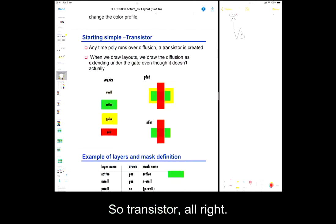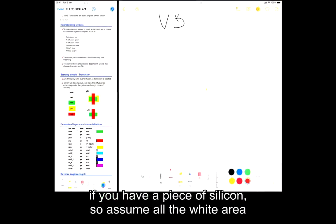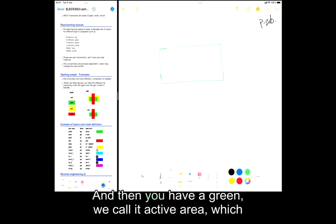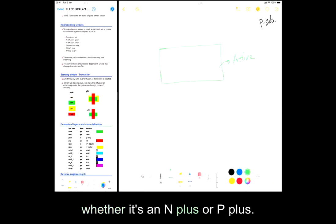So transistor. All right. Remember when I say on a piece of silicon, on a layout, if you have a piece of silicon, assume all the white area is your substrate. So assume this is a P substrate. And then you have a green area, we call it active area, which means it's heavily doped, but you haven't specified whether it's N plus or P plus.